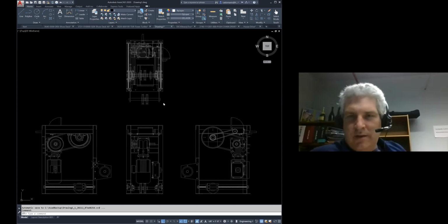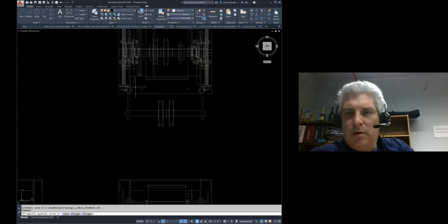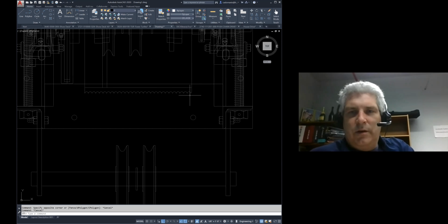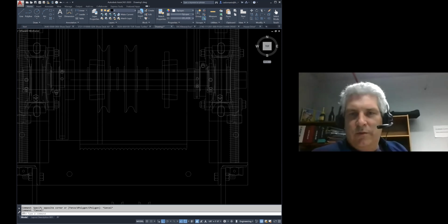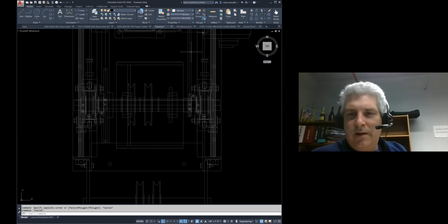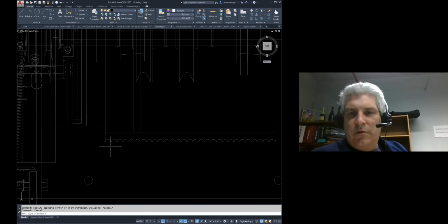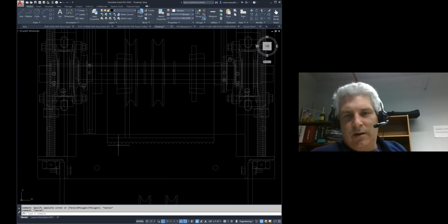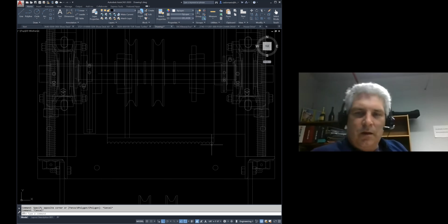And then I think the key to these machines for everybody is the fact that we're using typically a grooved cable drum. So that is a helically grooved, i.e. the equivalent of a bolt style thing, such that as the drum rotates, the cable piles on and moves and makes its way across the threads of the drum, to give you that take up technique.